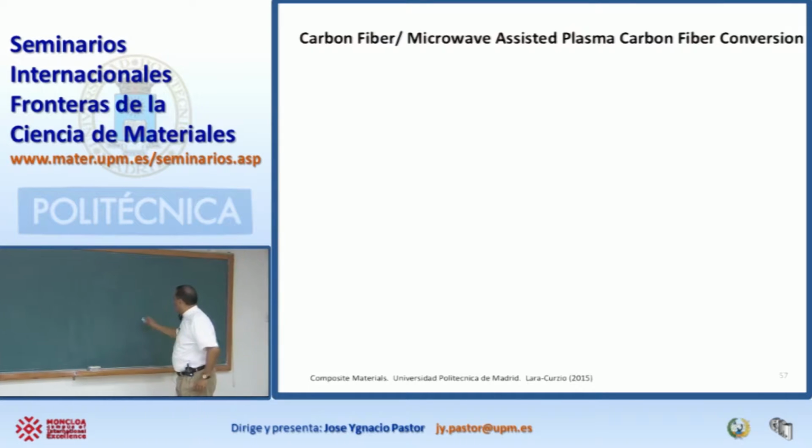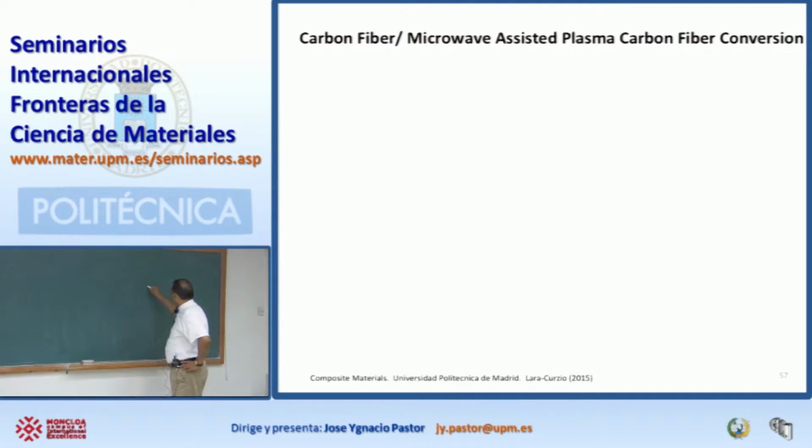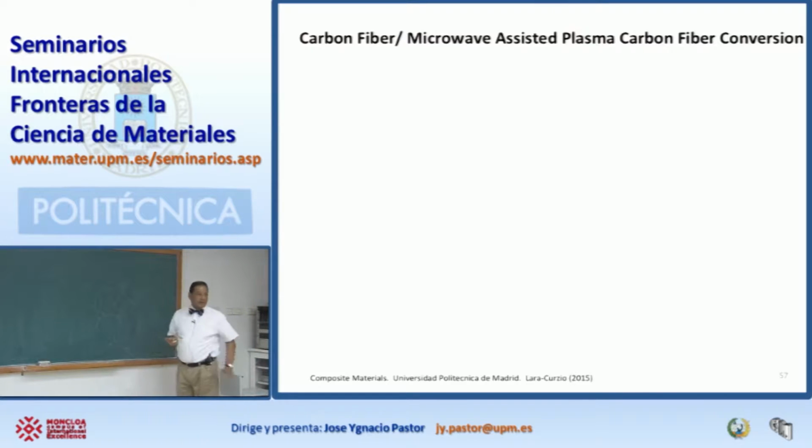In the case of carbon, so you have carbon, okay? And these are what we call the basal planes of graphite. So graphite is made by having many of these planes stacked one on top of each other, okay? So we call these the basal planes. Now, between the planes, they are connected by van der Waals forces. These are very weak forces. But on the plane, these are very strong covalent forces that keep the carbon together.